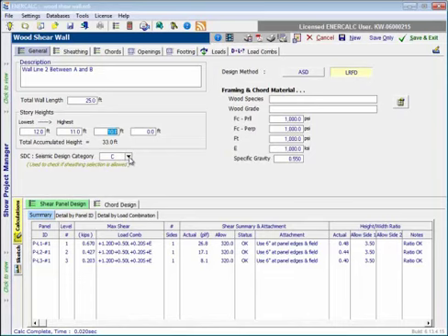The seismic design category is provided here in a drop-down list box form, and the purpose of the setting here is to check to make sure that the sheathing that we eventually choose on the next tab is actually allowed, because the 2008 version of the special design provisions for wind and seismic do provide some limitations on the types of sheathings that can be used in different seismic design categories. So we will collect that for you and then flag any conditions that are violated downstream.